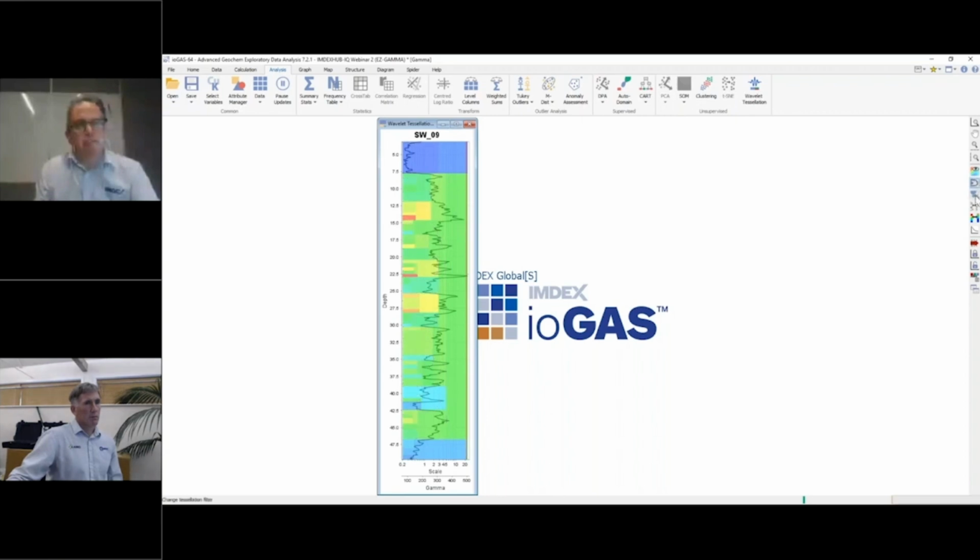We can filter at different levels. What this does is filter based on the strength of the boundary or the feature at the lower scale. So if we increase this, we start to lose some of that fine detail that's likely more noise than features in the gamma data itself. We can also change the coloring mode from normal linear coloring scale to log coloring scale or percentile coloring. This is good if you want to highlight certain features.